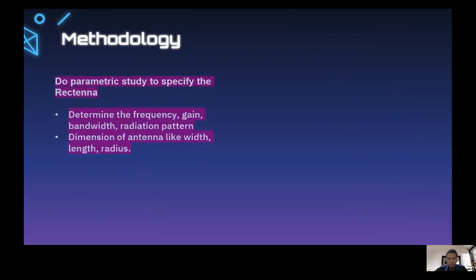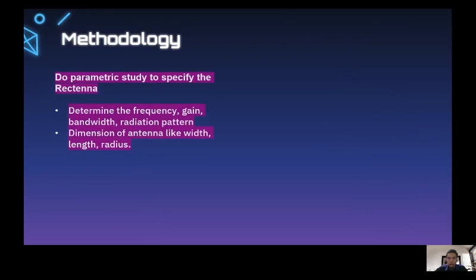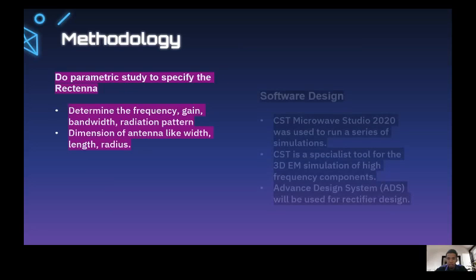Methodology. For methodology, I have done a parametric study to specify the rectangle, like determining the frequency, gain, bandwidth, and the radiation pattern. The next one is the dimension of the antenna, like width, length, and radius.